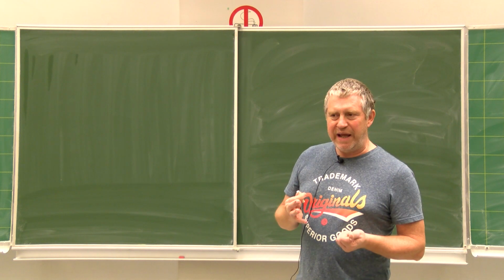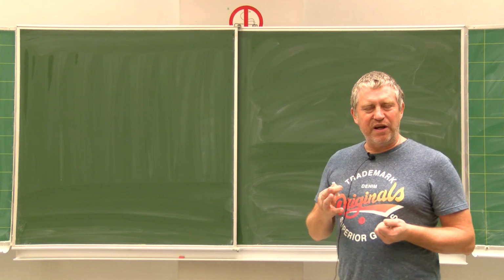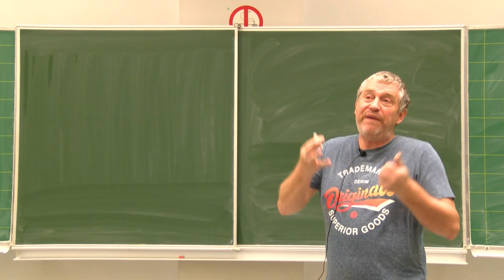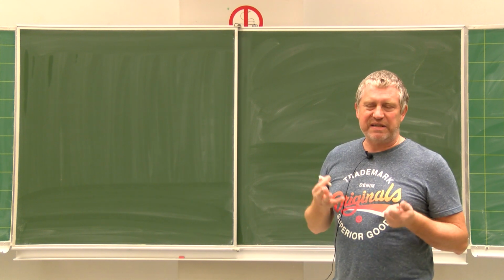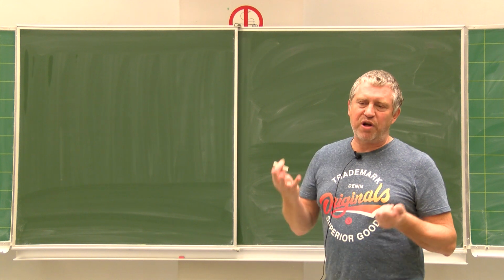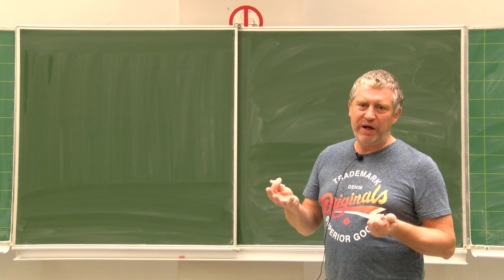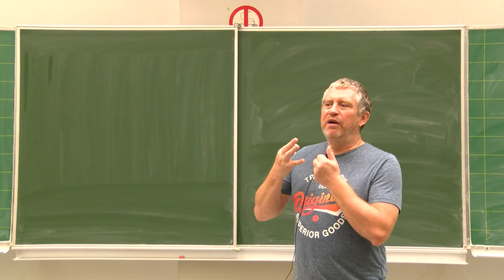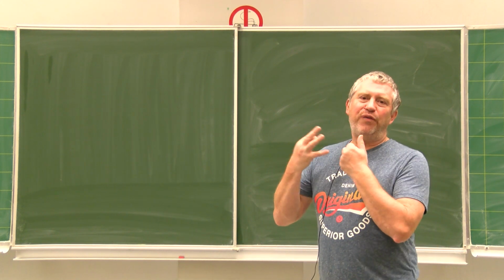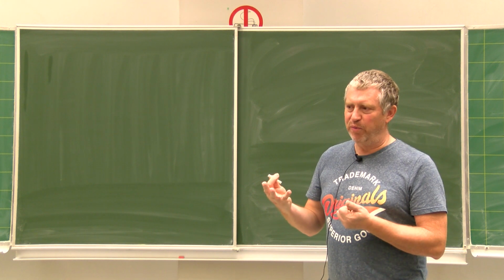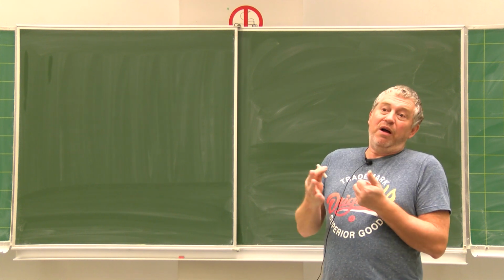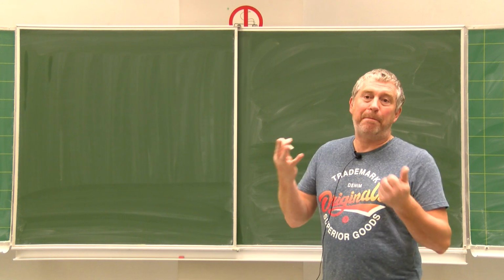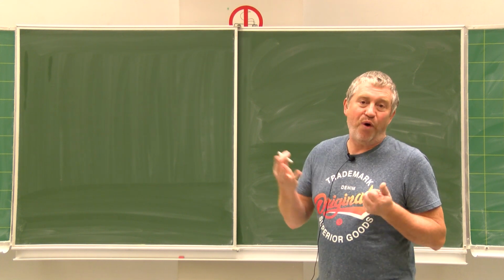And that's why today we will also study a second cycle. It will be, in fact, our fifth cycle. That will be a cycle with what we call post-combustion or afterburning. That will be there not anymore to fight against fuel burn, to reduce the fuel burn, but to go once again to the other parameter, increasing the compactness, increasing F over m dot.